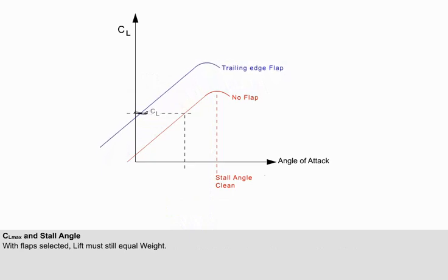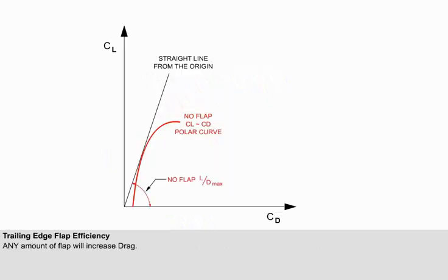As the flaps deploy, the pilot must reduce the angle of attack so that the effective angle of attack remains constant, and that lift still equals weight. Please remember that any amount of flap will increase drag.